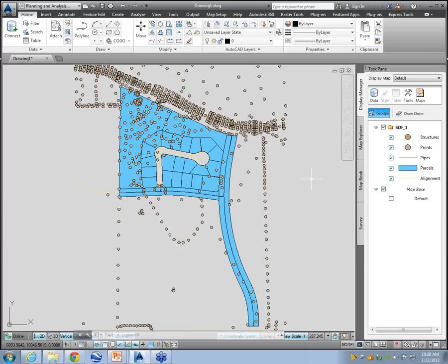So I've got my SDF file. I've got to remember where I am and all my notes. So I've got my SDF file in there. How do I add extra information to it? So as I mentioned, if you export out of Civil 3D, you've just got this one file. But now that I've used this one file, I want to create more and more and more. Okay, couple things. To add extra information into a layer that I've already got.